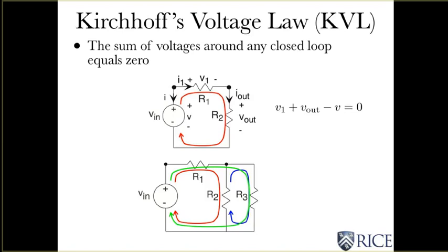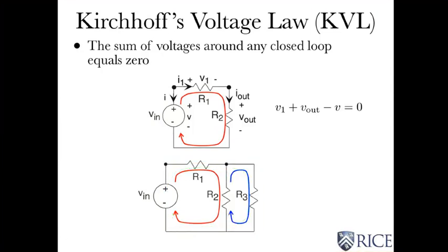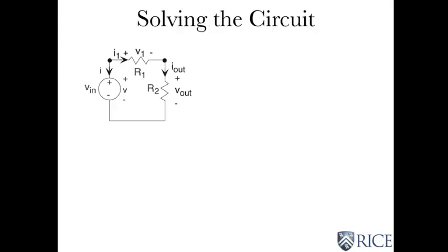If you thought about this as a window, and these were pieces of wood holding together the pieces of glass, the number of KVL equations is the number of pieces of glass. In this case, 2. So the number of KVL equations I would write would be 2, and I'd write it for each pane of glass, if you will. So that's how you find the number of KVL equations that you need to solve for any circuit.